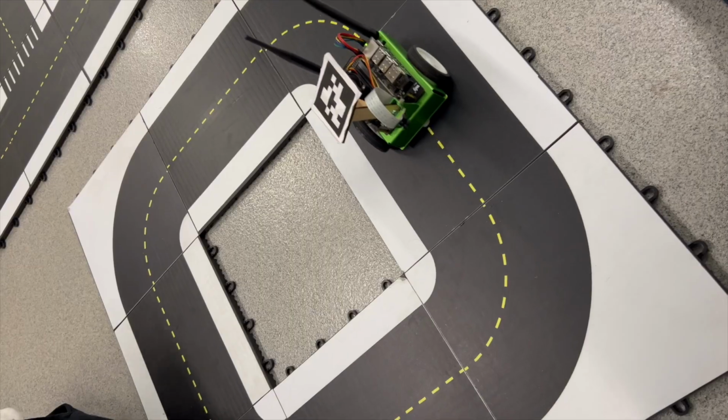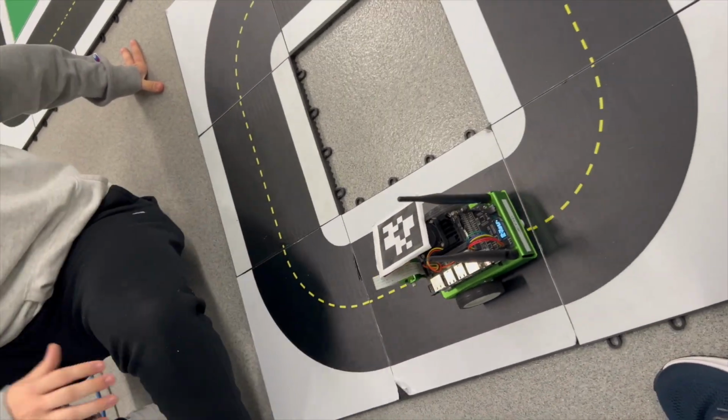Lab 2 was first about using the camera attached to the JetBot to follow the yellow line in the middle of the road using HSV values to focus on the information that is needed by the robot. Then we had to use robot kinematics and camera feedback to be able to follow the path created, a big circle in this case. This was done by feeding the heading angles of the robot to complete the turns. From there, code was created to have the robot turn to center the yellow line between the two wheels and in turn stay on the road.